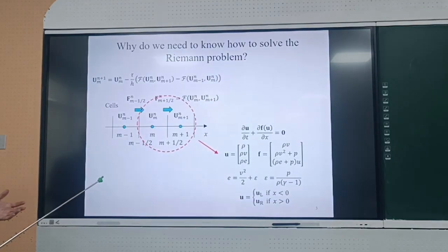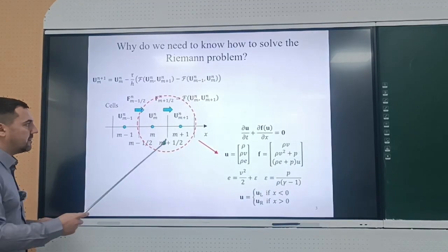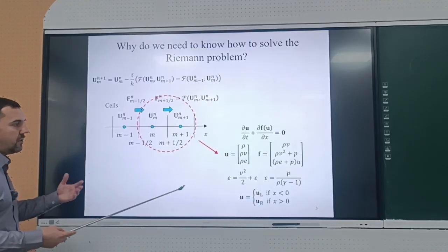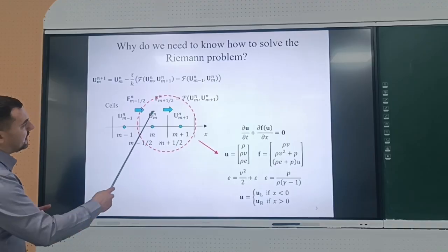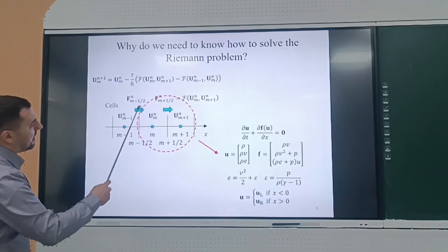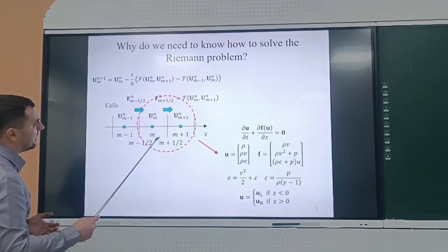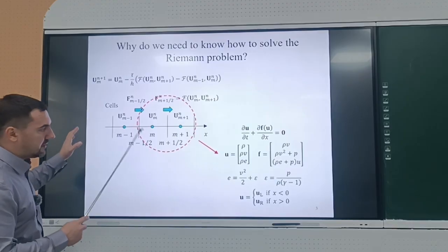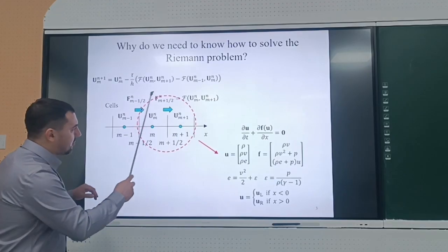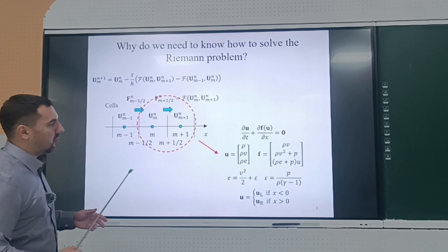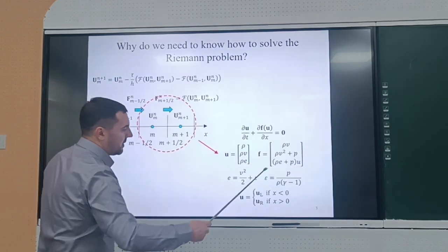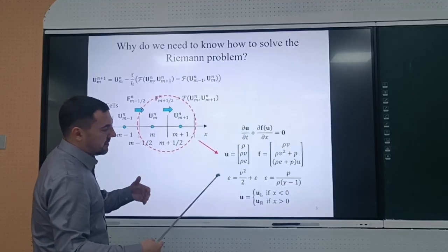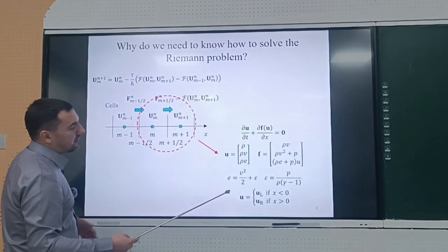We discussed the transition and the coupling of this numerical method with the fundamental problem for the Euler equations. Okay, we need to compute the numerical flux through this boundary between U_m^n and U_{m+1}^n. Let's forget for the moment about the numerical method and consider this as just the Cauchy problem for the Euler equations with a discontinuity in the initial data.